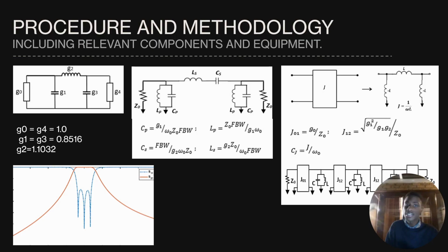However, our circuit is not yet finished. As mentioned previously, our circuit design will be a J-inverter circuit, featuring inductor-only networks. We will use the prototype filter to derive the values for this new J-inverter circuit and calculate accordingly. When simulating, we should get a result with our desired center frequency. If it's not in that range, we can tune it so that we get to that desired frequency, or as close to it as remotely possible.